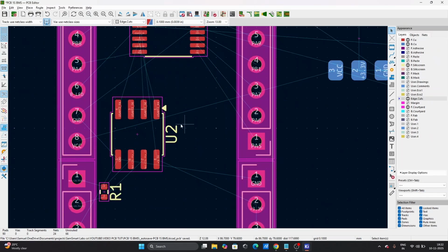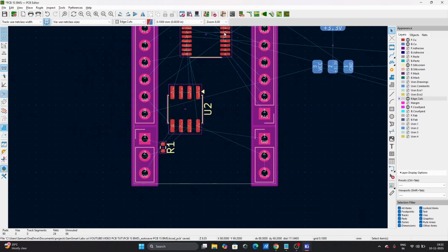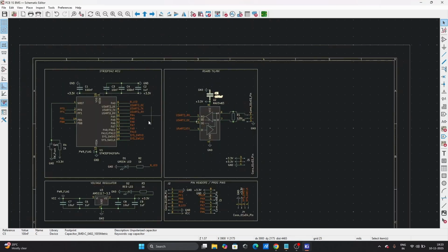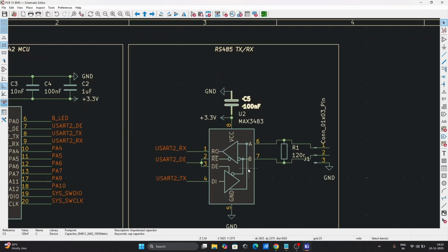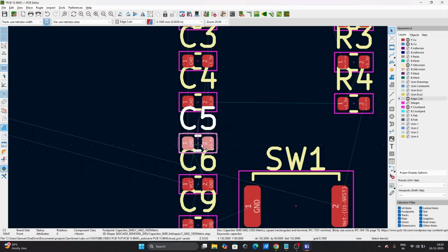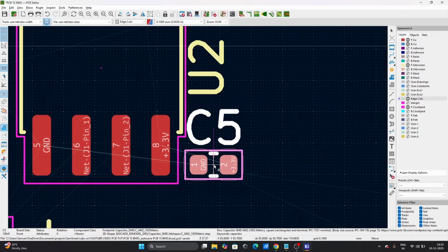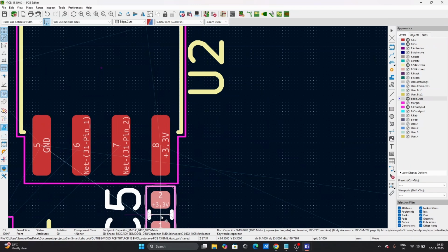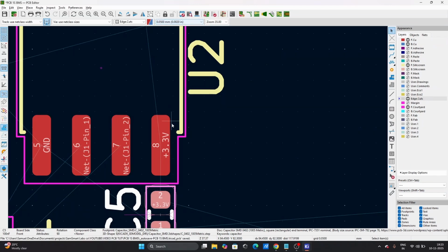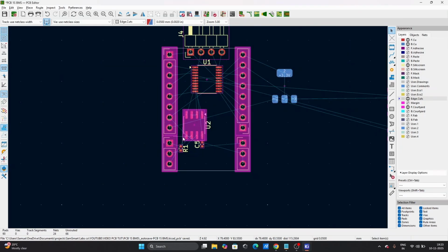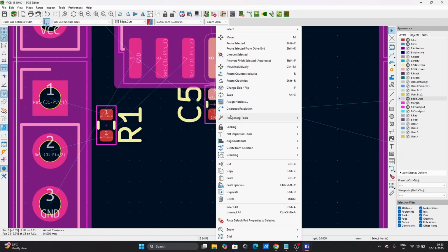So how I do it to get everything closer very quickly, for example, now I'm working with this guy, so I can just select all the components that are around here. For our case, it's just these two, so I'm looking for my decoupling capacitor for that guy, so just bring it close. I like to keep the decoupling capacitor as close as possible, so I just keep it right here in front. Can change the pitch now to something smaller. I like working with smaller pitches. I'll lock this guy in and I'll just observe to see how everything is looking.